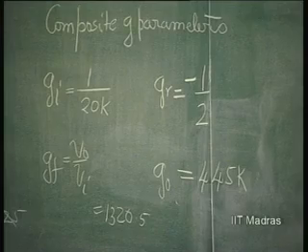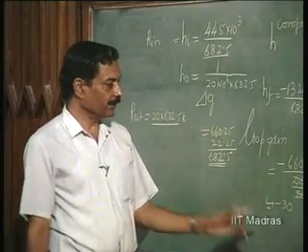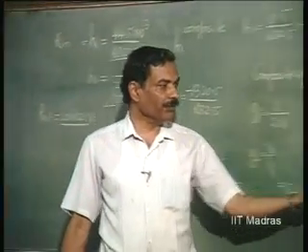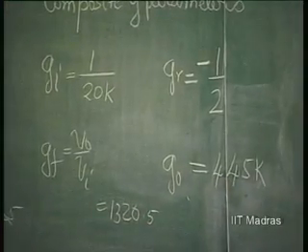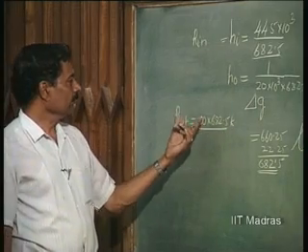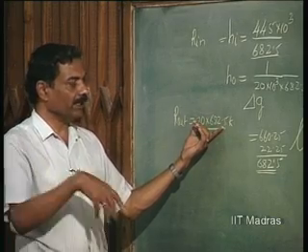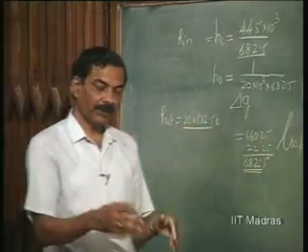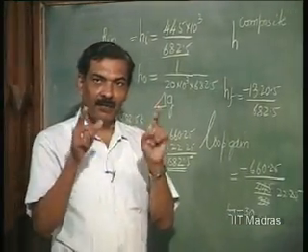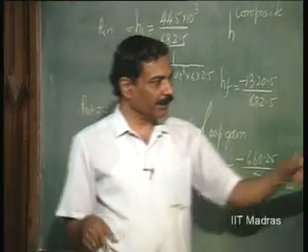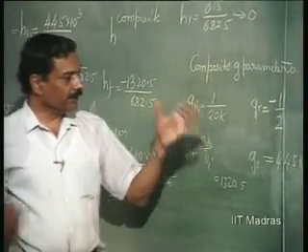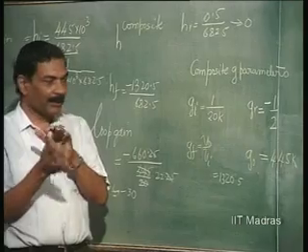Everything is going to change by 1 plus loop gain. Loop gain is 30, so 31. So, 445 into 31 is again this, the 445 into 31. So, you will get this by the other method also. Input impedance increases by what factor? 1 plus loop gain. Original input impedance, if it is something, input impedance increases in the case of H feedback.